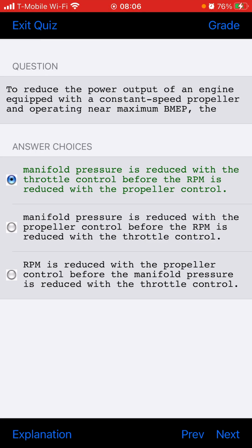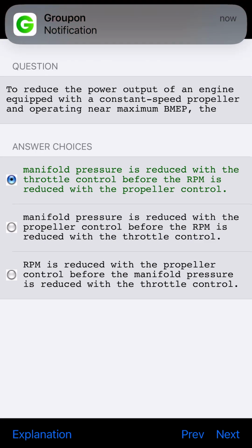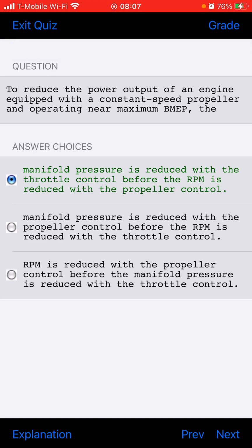Which condition would be least likely to be caused by a failed engine bearing? Low oil temperatures. All the alternatives except low oil temperatures would likely be caused by failed or failing engine bearings in the reciprocating engine. Low oil temperatures would be least likely of these alternatives.